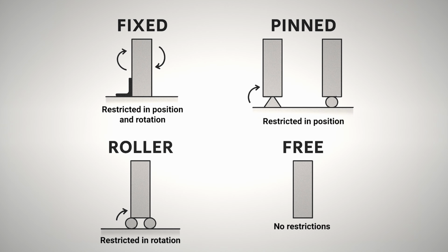Effective length is a fundamental concept in structural engineering, particularly in the design of compression members such as columns, braces, and some beams. It refers to the length of a structural component that is effectively free to buckle, considering the support and restraint conditions at its ends. The effective length plays a crucial part in determining the member's stability and its critical buckling load.